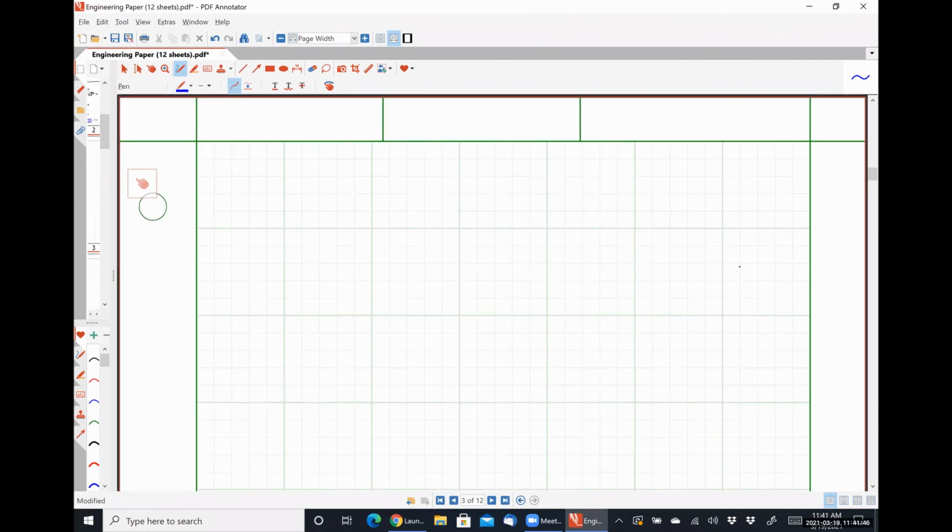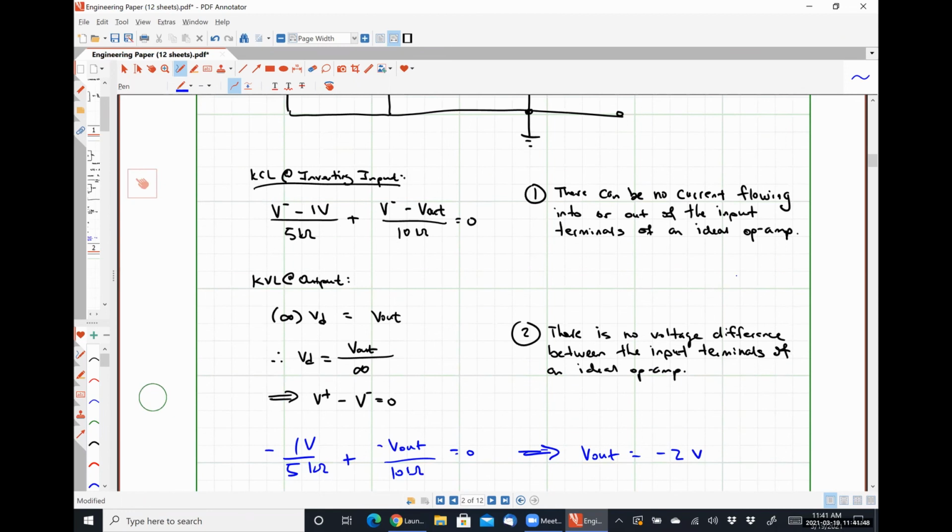The difference between them is what is called the gain error of the system. And if the open loop gain of your op amp is very, very large, your gain error is very, very small. So for negative feedback op amp circuits and negative feedback op amp circuits only, from here on out, unless you are told otherwise, treat them as if they were ideal op amps.